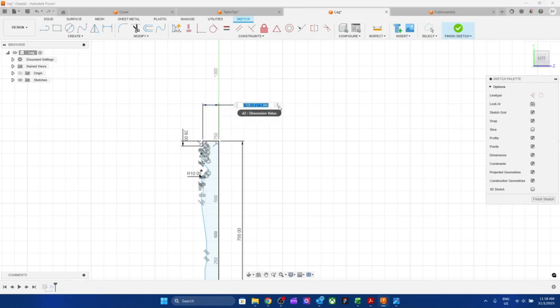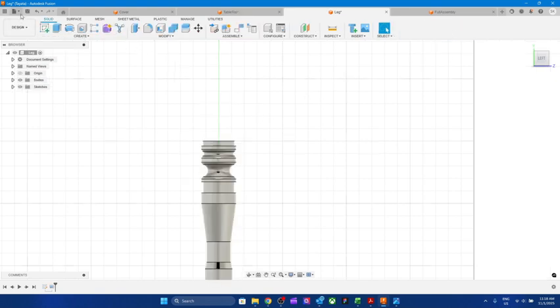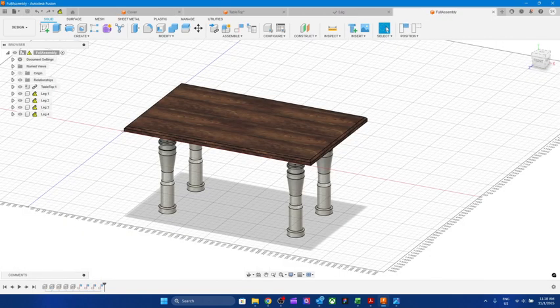So we could simply put the dimension, let's say we want to make it 62, in order to make that. So now this has become 0.5 smaller, yes? Yes. The whole is 65. So click OK. So design has changed now, and click Save. When you go back into assembly, it will not give any drastic problem.